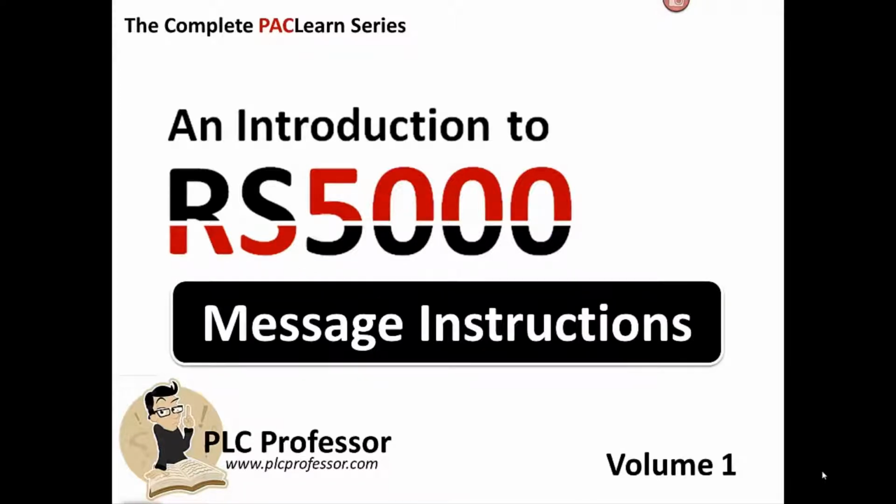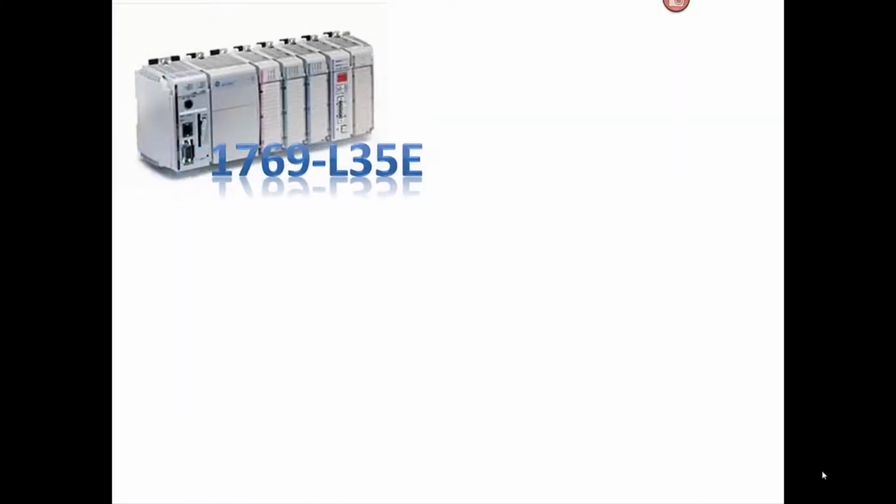Explicit messaging between two processors that both use the Logix engine and another processor from an older family. And the hardware that we're going to work with, we have a 1769 L35E. We're going to start with that. And the 1769 family of CompactLogix was made up of an L20 series and an L30 series. This is an L35E, and if you look at the front of the processor, which is the leftmost module, you'll see a key switch. Below it you see an Ethernet port, then an RS-232 port, and then just to the right you see a slot for a memory card.